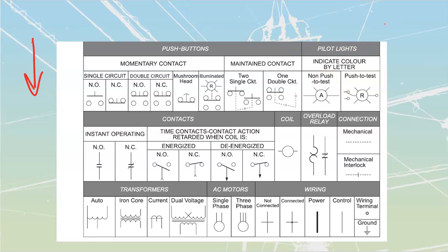Really handy when you've got sealed processes, stuff that is happening inside of a pit that maybe you can't get into, or inside of a drum or something like that. You want to know if the heater is on inside of the drum. You can't just open it up because you've got a process under pressure or something. You can push that push button and say, yeah, the push button is not calling for it, so it must be off, but I can check that my circuit is correct or that my light bulb isn't burnt out.